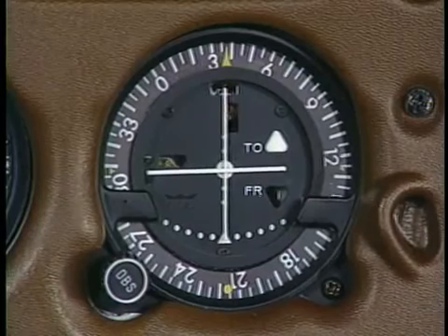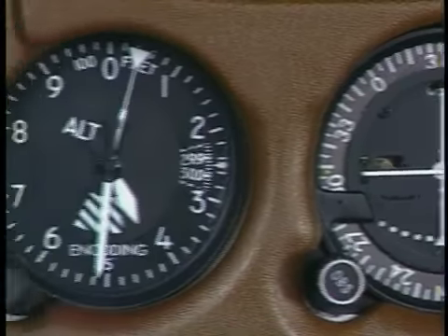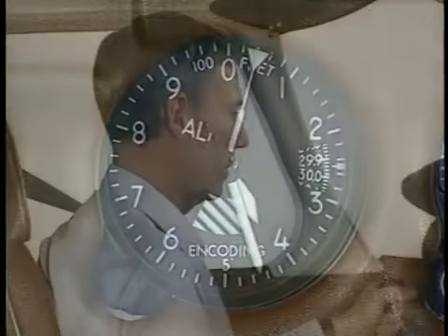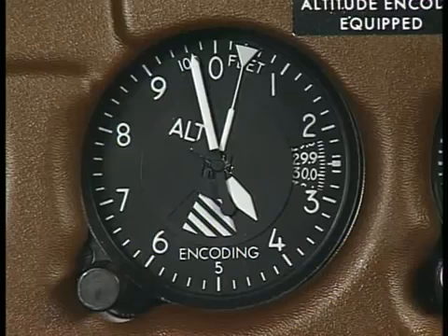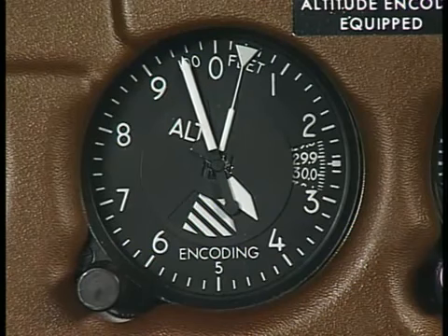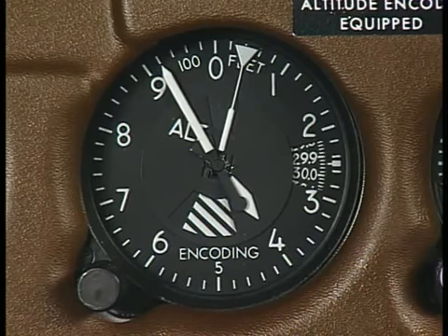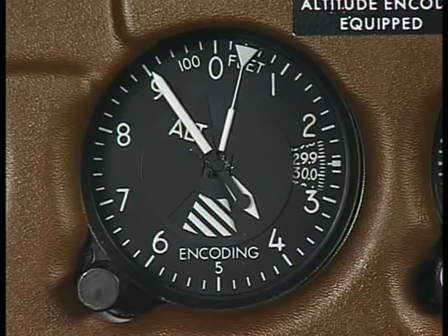As you continue down the glide slope, you should monitor your progress toward the decision altitude and height. As you approach the decision altitude, begin to look for the approach lights and other indications of the runway environment. The missed approach point on this ILS is located where the glide slope intersects the decision altitude of 3,805 feet.